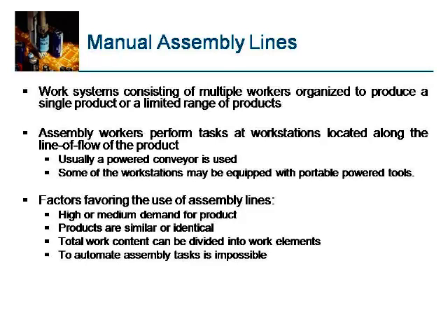You can do it in a line fashion, or you can do it in a U fashion, or you can do it in a looped fashion. Anything is acceptable. Depending upon the space constraints, you need to design your assembly manufacturing system as per the space available to you on your shop floor.